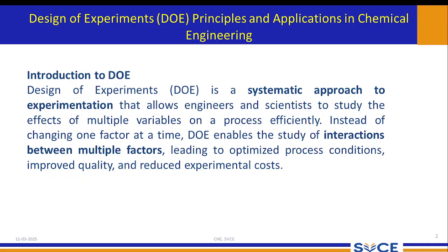Let's say you have pressure and temperature. How the pressure or temperature or both will affect the yield, and also the interaction between these factors, how it affects the yield, leading to optimized process conditions, improved quality, and reduced experimental cost.